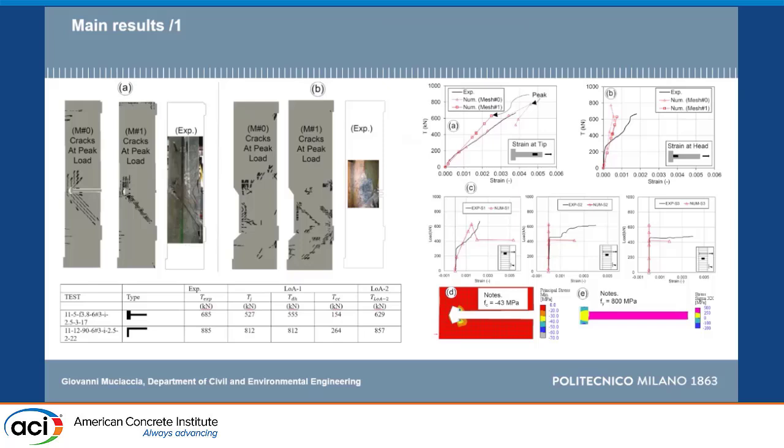Which are the results? How much time do I have? I can show some of that. So first, the crack pattern. The crack pattern is comforting in the sense that the crack pattern observed from numerical simulation quite well resembles this picture which you see here from experiment. So this was identified as concrete breakout by the author.